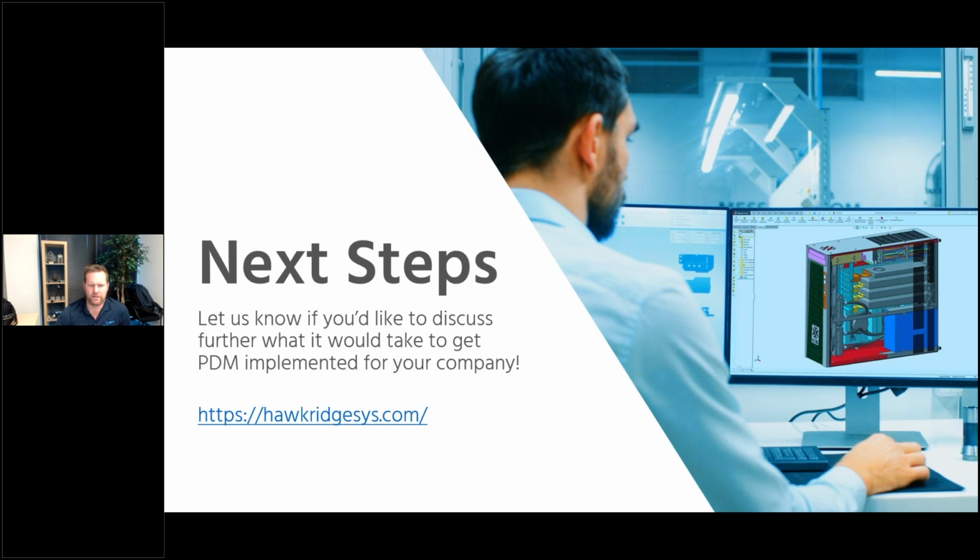Parameter called vendor inside of SOLIDWORKS part. How would we display that? Yeah, so you just map that vendor to a variable in PDM, and then just make sure you include vendor as a column. I'd mentioned to Peter that's something we have an entire dedicated team. I'm actually part of that team, our enterprise solutions team here at Hawkridge Systems. That's all we focus on, is setting these things up, understanding your guys' issues, and then figuring out what the best solution for that is, best scalable solution for that is going forward. So feel free to let us know, and we can always have a conversation around that. Maybe a little brainstorm session. Those are my favorite.